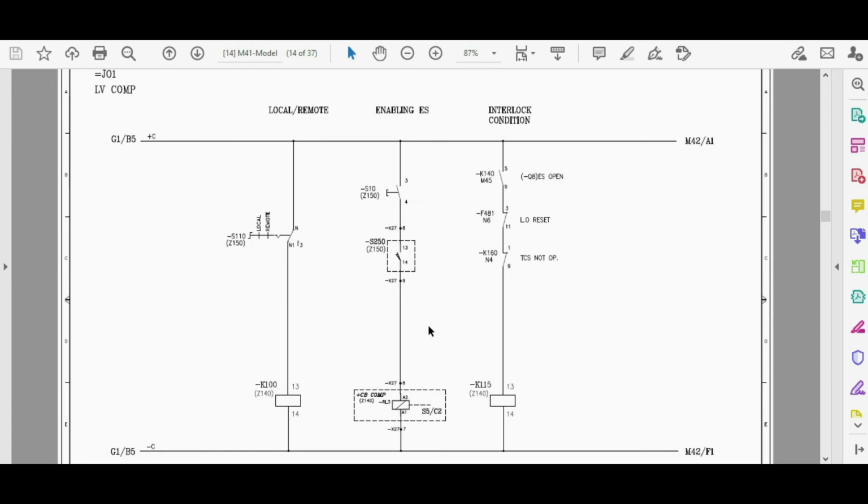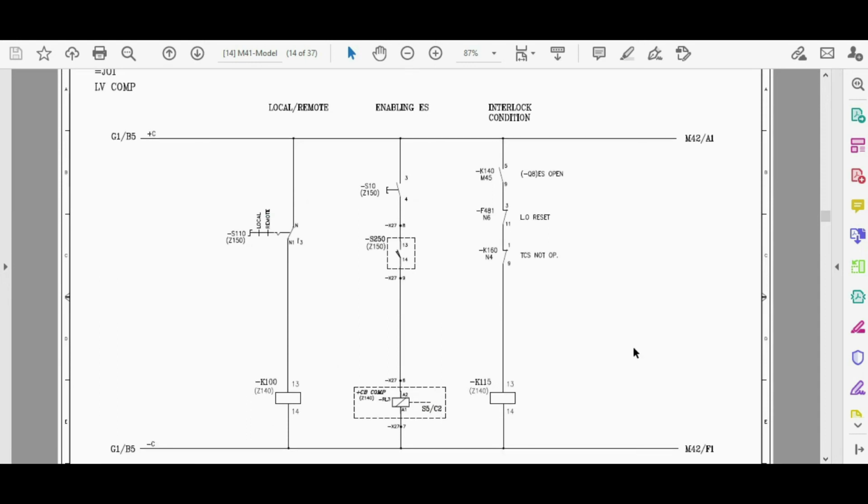Then in this situation, the operator moves the handle, puts it in the earth mechanism and turns it clockwise 90 degrees. For the next 90 degrees, he must push it a little bit more until the earth switch is closed or opened. I've shown it in the previous video.